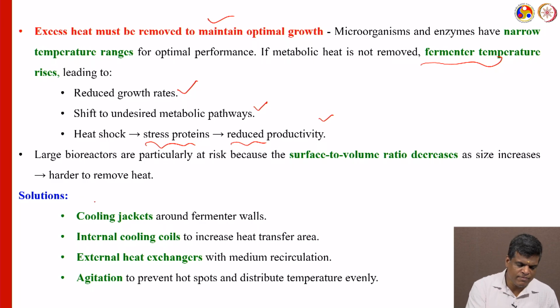So, what are the solutions? Same as before, we have to use cooling jackets around the fermenters, or an internal cooling coil, or sometimes an external heat exchanger or agitation here. Then the excess heat can always be avoided.